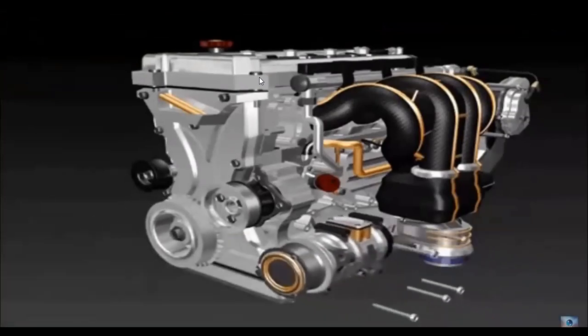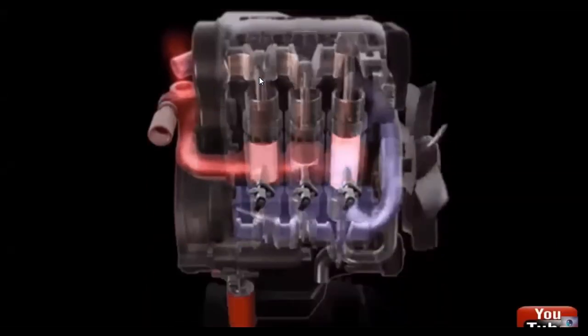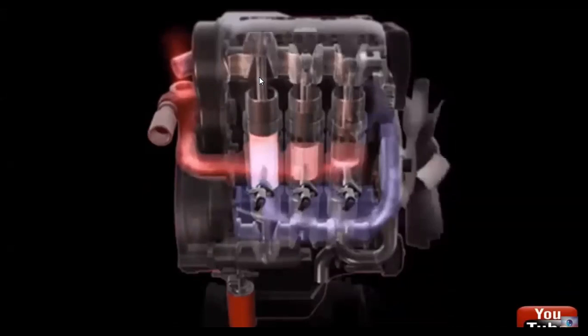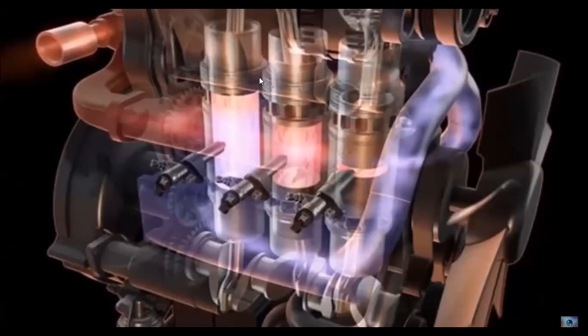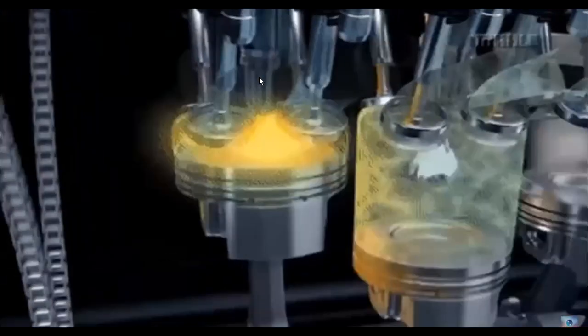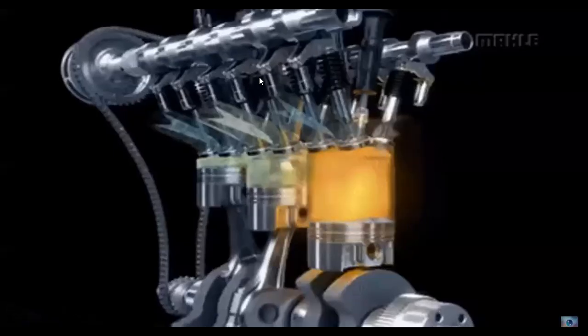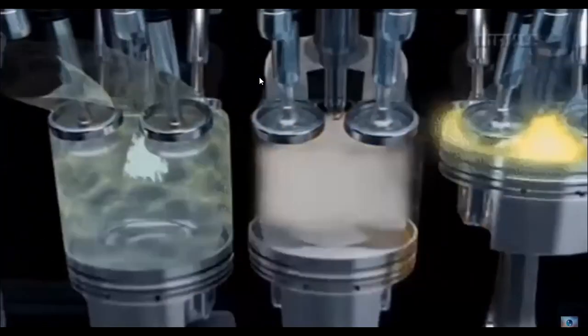Internal combustion engines are the most broadly applied and widely used power-generating devices currently in existence. Examples include gasoline engines, diesel engines, gas turbine engines, and rocket propulsion systems. Internal combustion engines can be described in terms of a series of thermodynamic events. In the continuous combustion engine, the thermodynamic events occur simultaneously as the oxidizer and fuel and the products of combustion flow steadily through the engine. In the intermittent combustion engine, by contrast, the events occur in succession and are repeated for each full cycle.